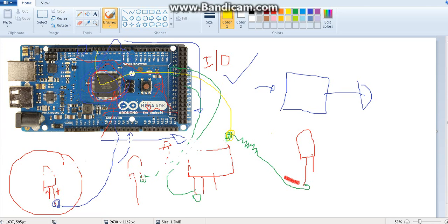Okay, this is totally fine. So this is a basic LED connection. You should be knowing this. Otherwise, you can look up how to connect an LED with a power source. You can Google that. The ground part, the negative part of the LED, should go to ground. We have a few ground pins in the Arduino. You can see GND. You can take a wire from here and connect the negative of the LED with this GND. So this is the basic LED connection. Now your LED is ready with pin number 7 of the Arduino, and the other side is connected to ground.